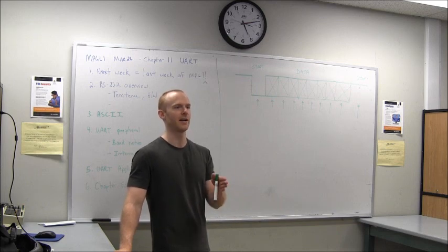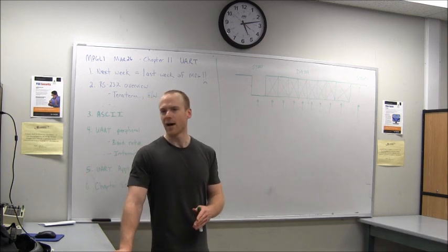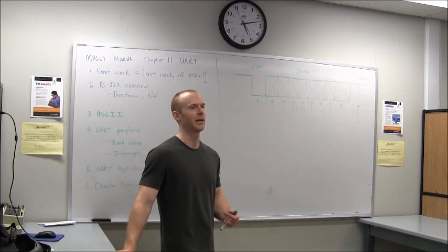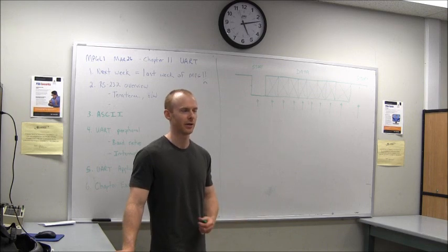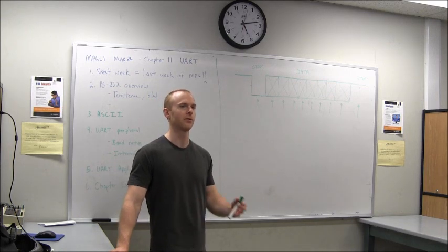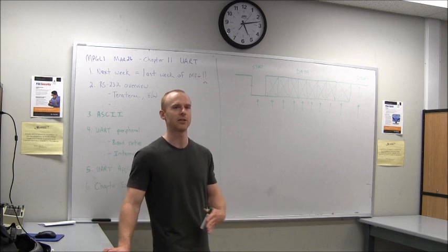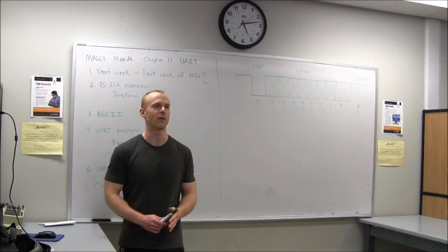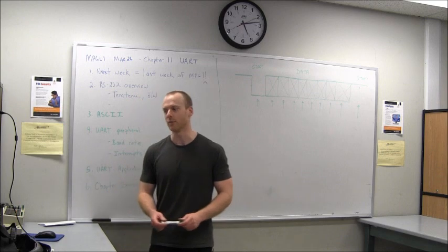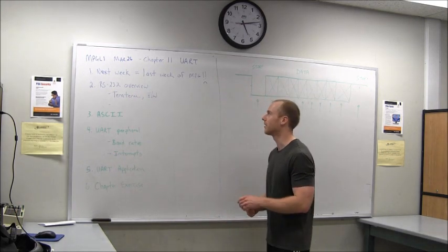So that's kind of the PHY, as they call it, the physical interface that the processor doesn't have on board, because I think it takes too much space and you've got to have a bunch of caps on there, so they don't bother incorporating that. Plus, most of the time if you're talking from one microcontroller to another microcontroller with UARTs, then of course you don't need that translation. But if you want to talk to a computer, then you stick one of those rather expensive, for some reason, chips on there. So you can check out the hardware for that.